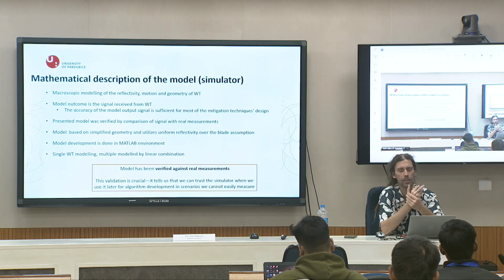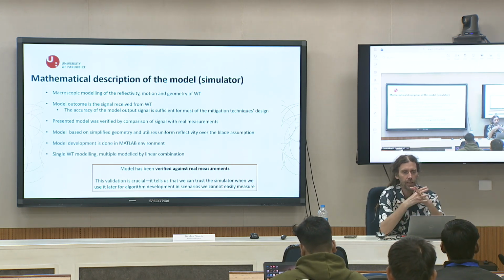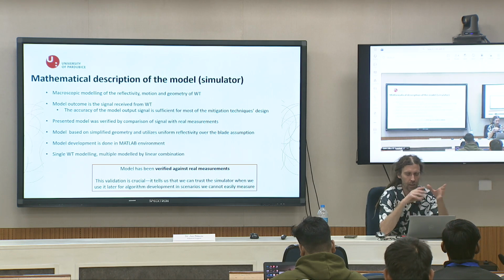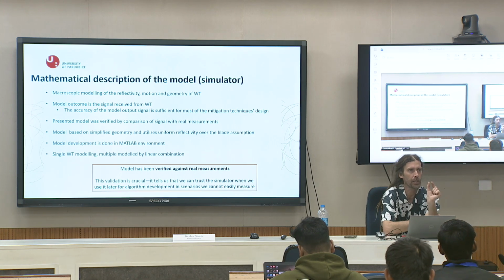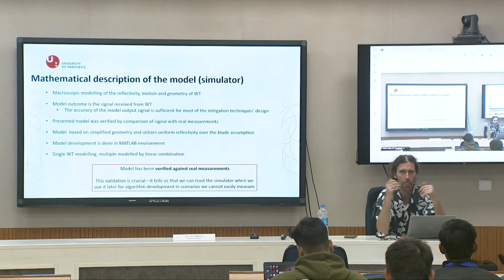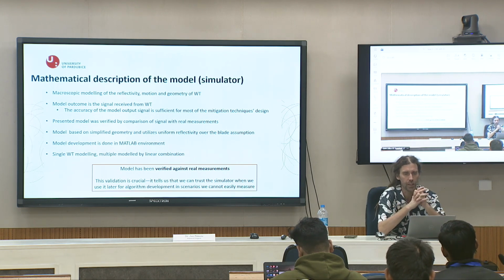What is the advantage? You can simulate any output, any input parameter that I already mentioned, and you can also make lower or higher resolution. What is resolution? Length of blade element. It is variable. I can change it. Of course, if it is very short, computation takes longer time, but never mind. So these are the advantages.